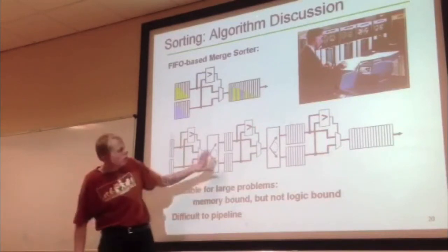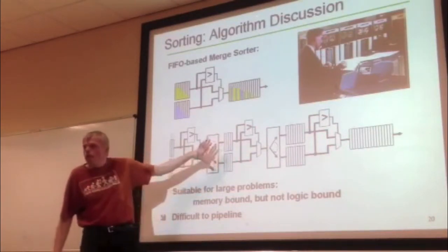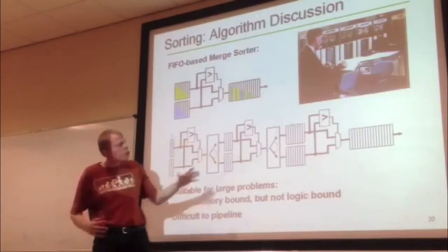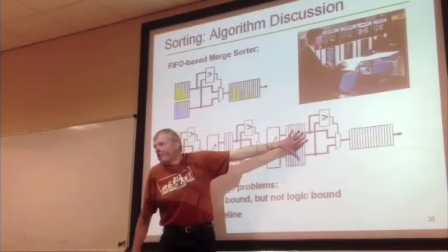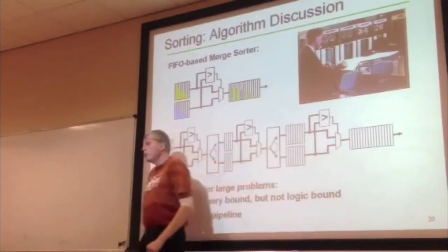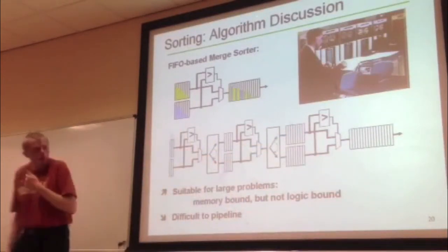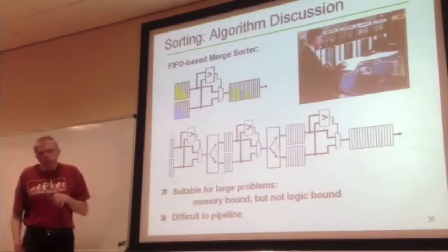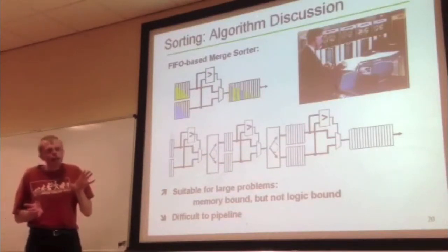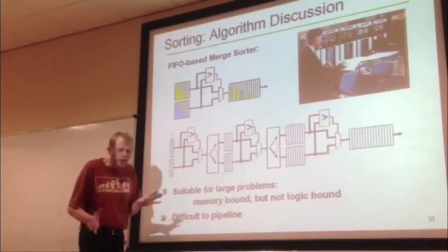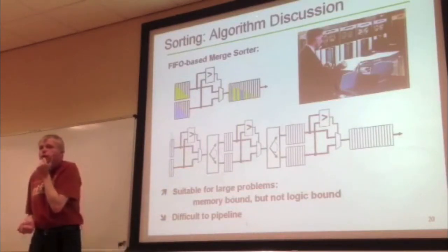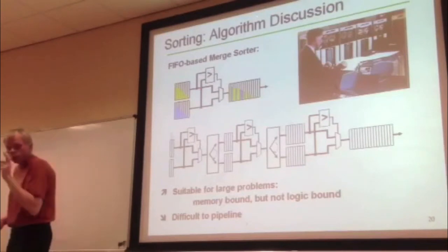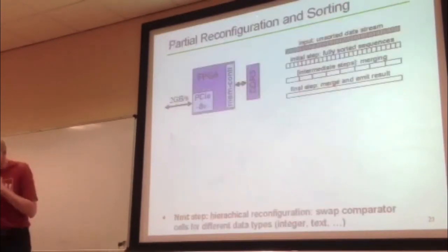But here you can assign the memory that's available on the chip as you need it for your application. And if a later stage needs more memory, well, you simply allocate more memory to it. And that's a really powerful thing. Another thing is also you can implement any arbitrary data dependency on an FPGA. While if you use a GPU, for example, everything is done via shared memory. This is good for some things, but not for everything.